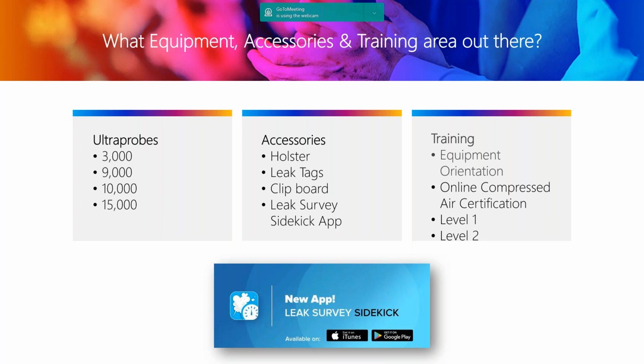Each of the holsters for each of the UltraProbes are fitted per that UltraProbe, and makes it where you can always have 3 points of contact on the ladder and that sort of thing. But also leak tags, definitely something that you'll want. And if you don't have leak tags, get at least surveyor's tape, something that you can at least go up, tie around the leak or the suspect area, so that you can hopefully document with the Leak Survey SideKick app. And then a clipboard.